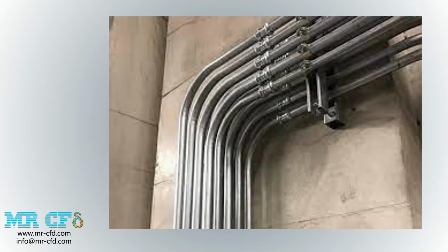Additionally, pipes can be cold or induction bent. Cold bending is performed by bending a pipe at room temperature, and this process is usually done by wrapping the pipe around the desired shape. On the other hand, induction bending is performed by heating a small section of pipe with an induction coil while continuously applying mechanical force to cause the material to bend. Both methods have advantages and disadvantages.